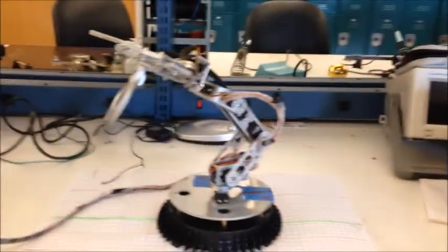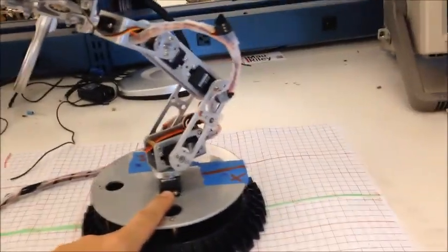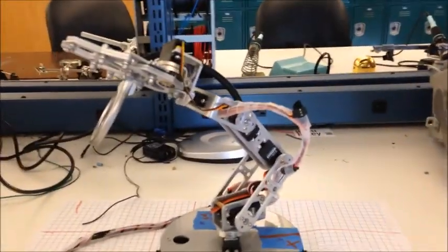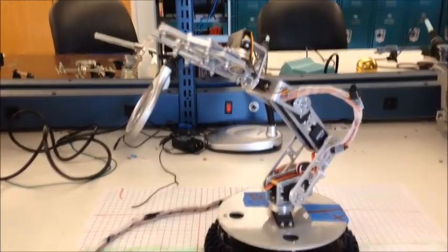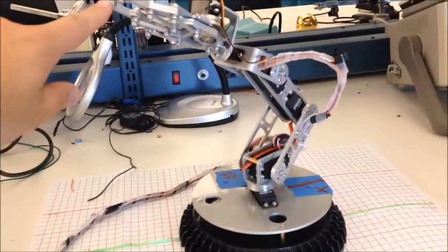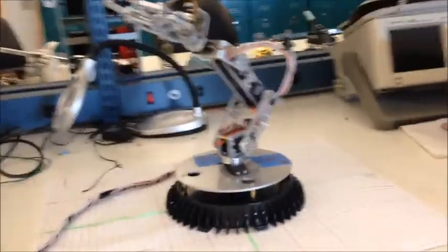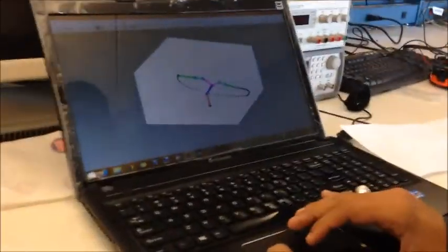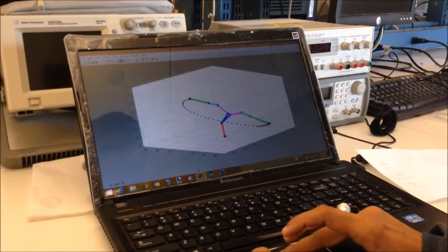And there's a slight difference here because the servo here at the base doesn't have the same range of motion as the simulated robot, so there's a workaround to get to the same position in space. So the trajectory might seem different, but the end location is the same, so you're reaching the same point in space, but it reaches it in a different way. And so here we are in the 3rd quadrant at a height of 24 centimeters. So in the simulation, what it shows first of all is it marks the location to reach by pink color, and then when it reaches it becomes black.